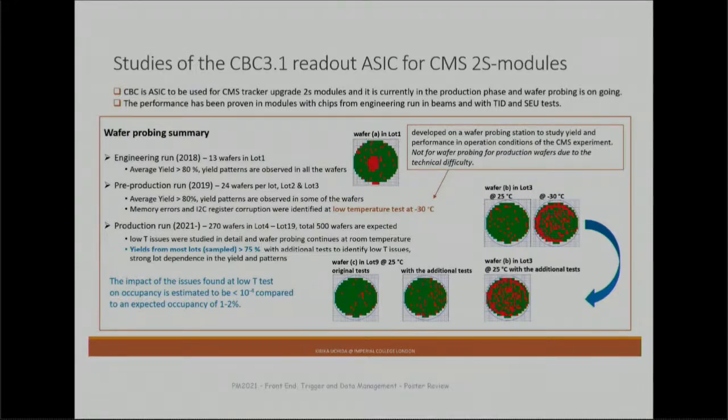They were looking for a long time to find out what the reason for this was. And it clearly had to do with the production process of the ASIC. In the production process, there is some polishing involved, and if the wafer is not completely flat, then you get these kinds of patterns. And the developers there found it very difficult to interact with the foundries, because these are very big organizations. They are not interested in changing anything in their process, so it really took a long time to cope with